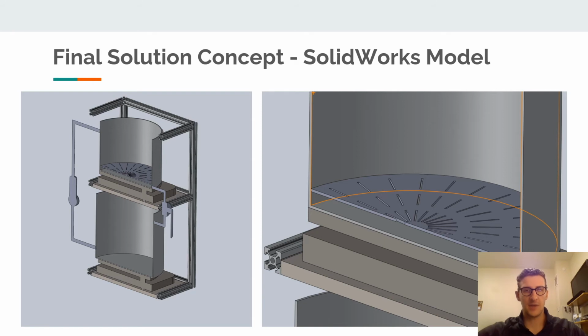And so looking at a cross-sectional view of the model, we see the straining aspect of the top tank. And so that false bottom plays a really important role in preventing large grains and particles from passing through onto the next step. And so once sugar has collected there, then hot water is used to sparge out the remaining grain sugars onto the next step.